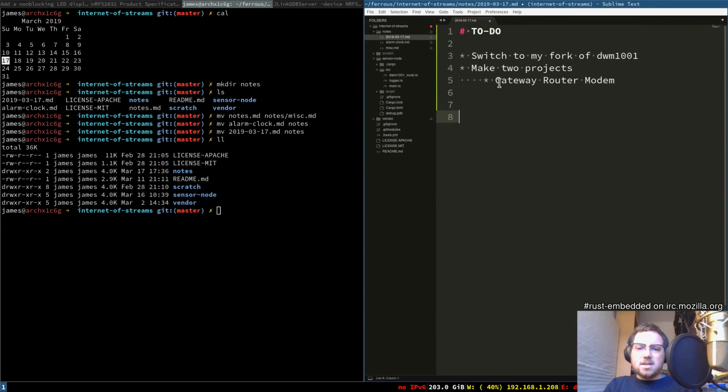Typically in IoT systems, some use common protocols like Wi-Fi, but the problem with Wi-Fi is it's not a super low power friendly protocol. So typically you have a way less common protocol, and you'll use something like 6LoWPAN, maybe Bluetooth mesh, maybe Zigbee or something like that. But the problem is most computer systems don't have those radios built in. You can't just buy a Zigbee router like you can a Wi-Fi router, at least not commercially. There are a couple, but they're not as widespread as Wi-Fi. So what you typically have is what's called a gateway router.